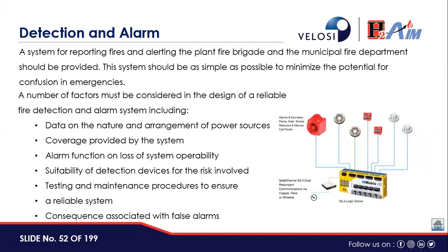These detectors are installed by designing a proper fire and gas detection layout with a due voting system, and the selection of these detectors is done as per the process requirements, and multiple combinations are installed. For example, if there is a gas detection, there should also be some heat or smoke detection, or toxic detectors in the same area, H2S is also there. So by a combination of one or two detectors, the event occurrence can be confirmed by the validation of two signals at a time.